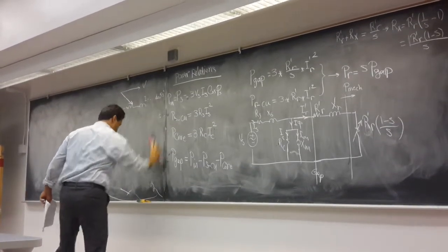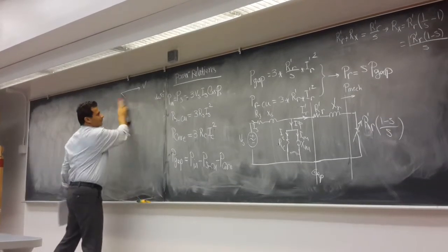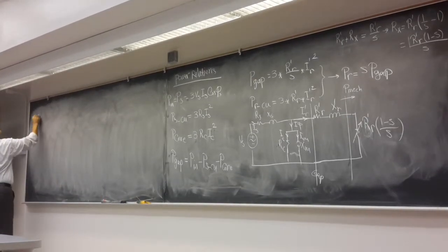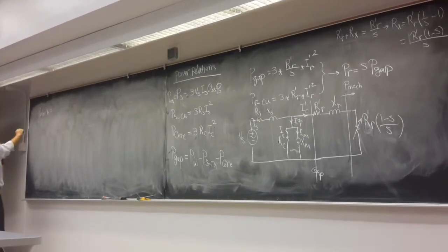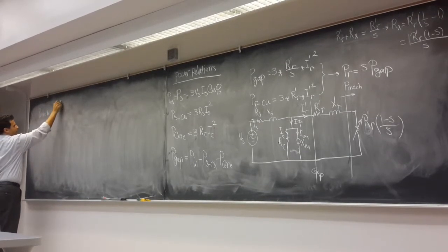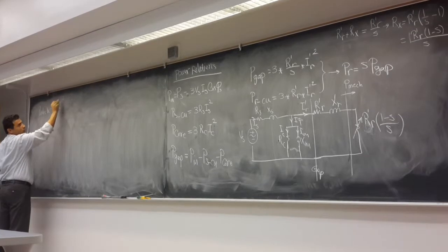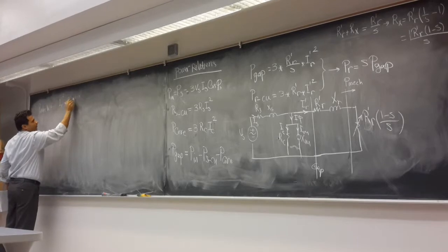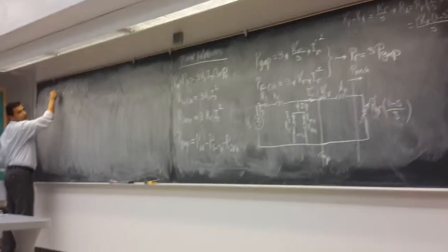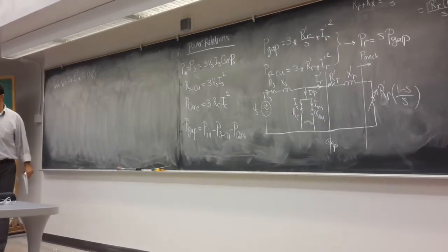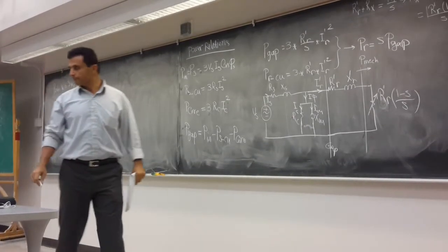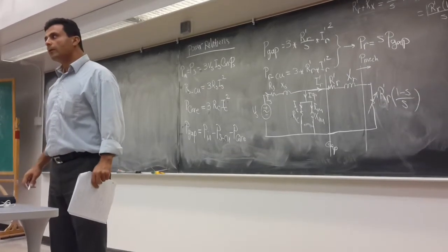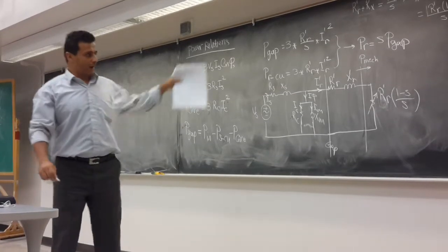I prime R squared times R prime R times (1 minus S) over S. Say, P net. How much is it? This is I prime R, right? Yes. To the power of 2, times R prime R times (1 minus S) over S, and times 3, because we have 3 of them, right? Why do we have 3? It's a 3-phase system, right? I thought it is the loss from the shaft rotating. If there's only one. No, that's after this one.